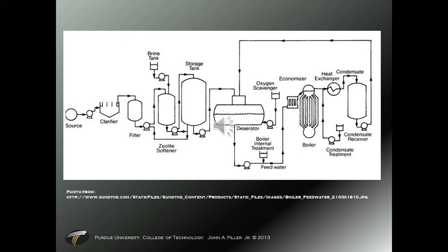The flue gas is hot. It's almost as hot as inside of the firebox itself, and that heat is then secondarily used to preheat the water. That's a second chance on getting energy out of that combustion cycle. So like I said, it improves the efficiency of our overall system.